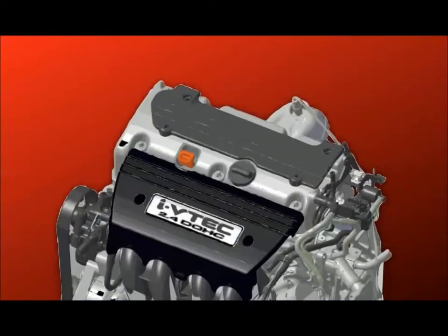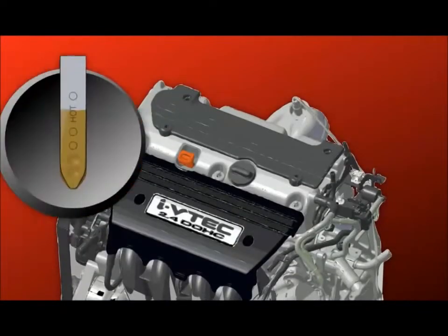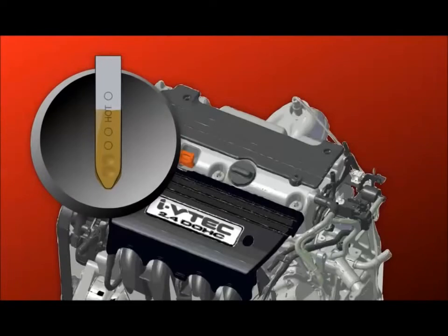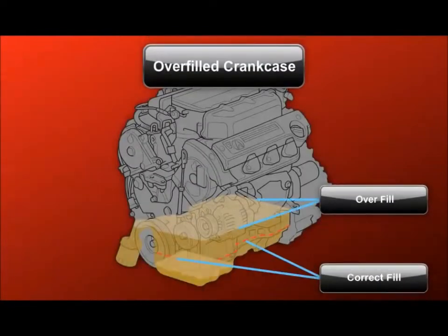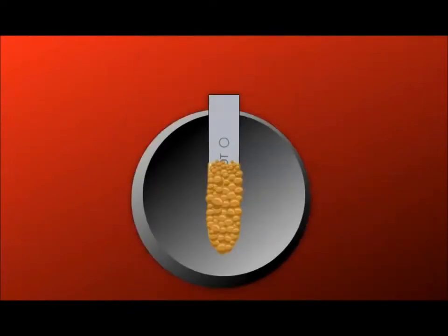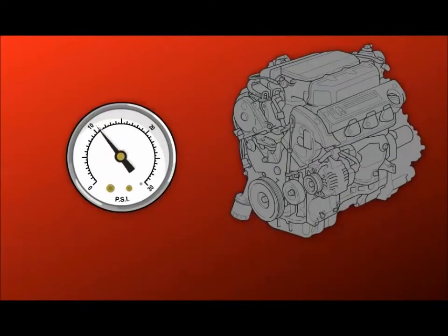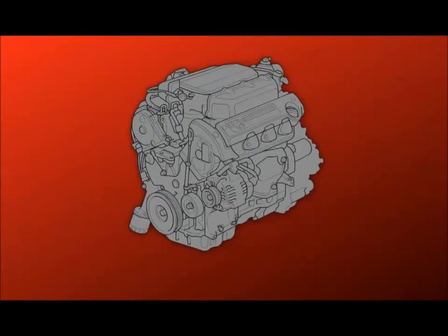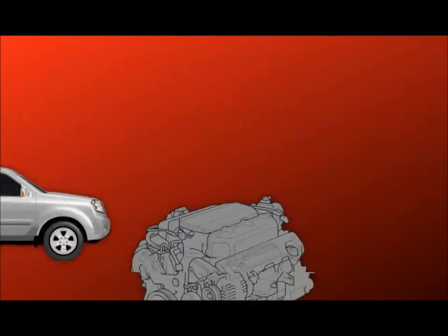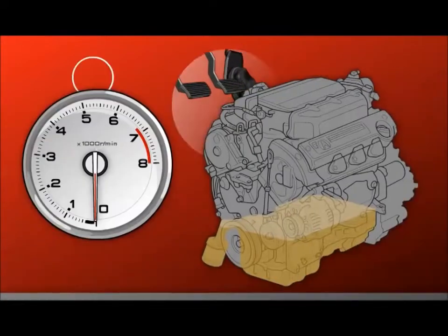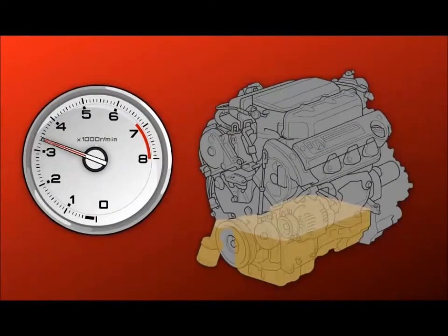Problems in the oil system start with the basics. For instance, the correct oil fill level is critical for proper oil system function. Too much oil can interfere with crankshaft rotation. This can aerate the oil, leading to low oil pressure and possible engine damage.